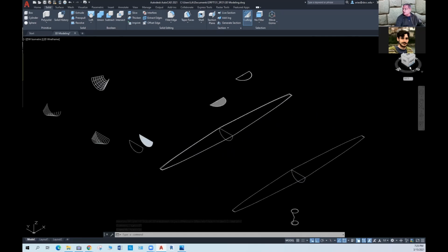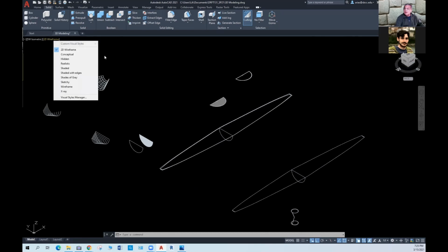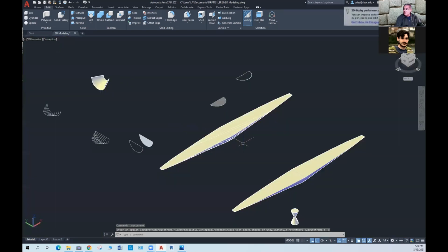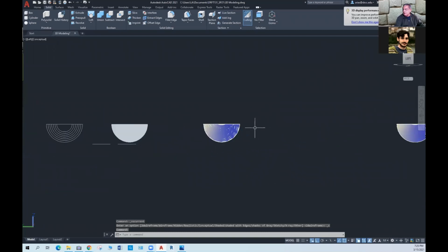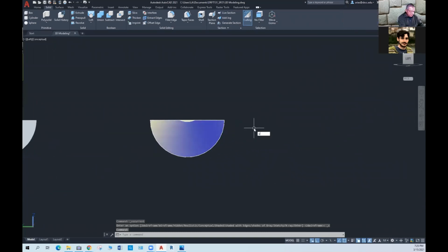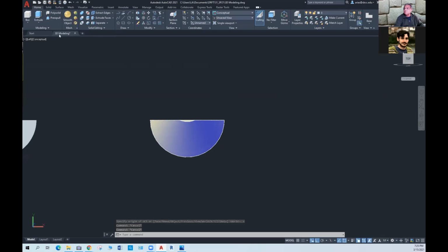Although a single way of doing this, what I want to do is kind of open the top, is to do UCS by view, and now create a polyline here.